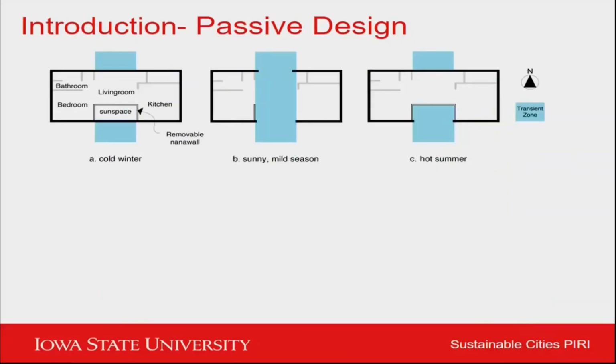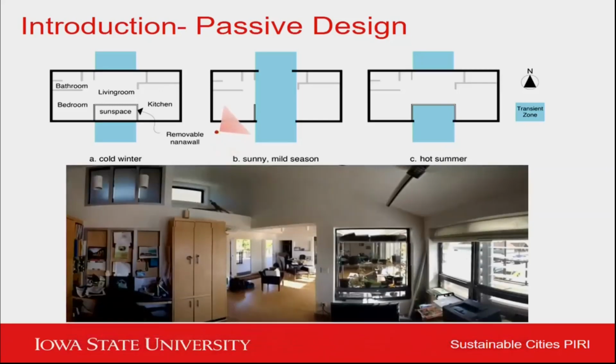And so in this climate, where you have 100 Fahrenheit, 38 degrees Celsius in the summer, high humidity, and minus 10, 20, 30 Celsius sometimes in winter, you still want to design with passive strategies in mind for the times when it's possible. You need to adapt the building footprint to the climatic conditions of the seasons. So we have cold winters where you try to reduce the envelope and you have a sun space, which is actually very effective because when it's very cold, it's also very sunny.